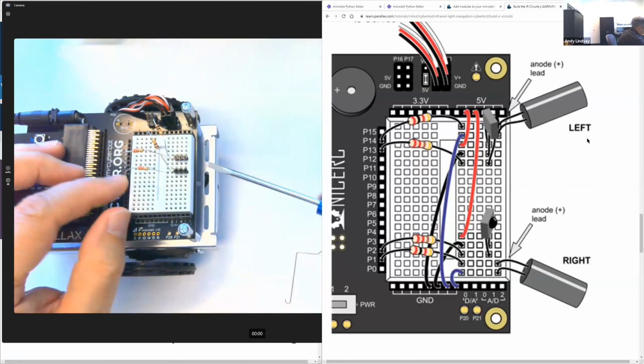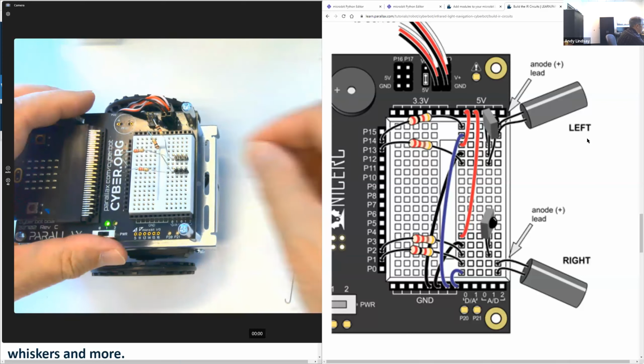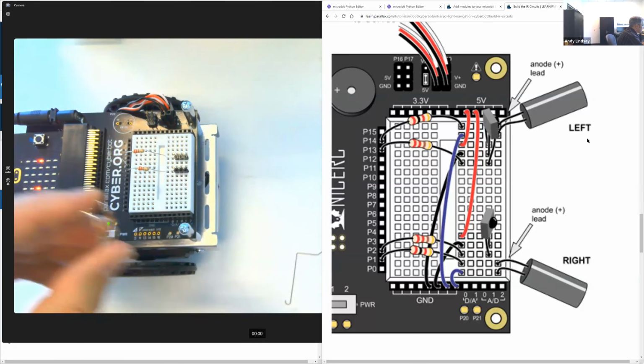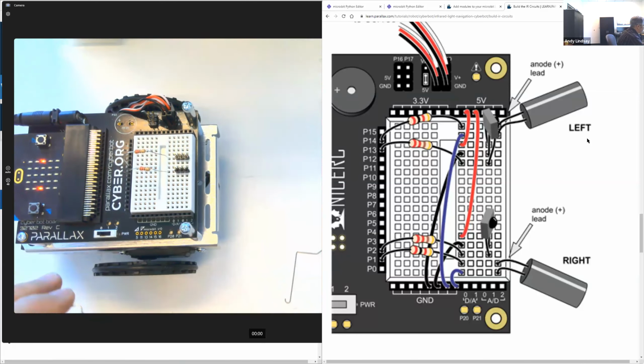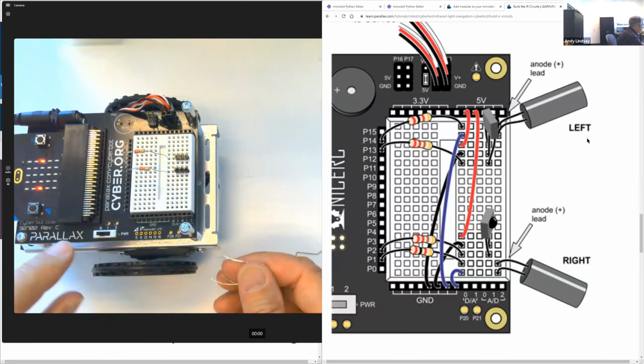You can actually save the red, brown resistors because you need those for the other circuit. So you can pull out the, oh, remember to turn your power switch to off. The PWR switch should go all the way to the right to 0. And then take out the 3-pin headers.